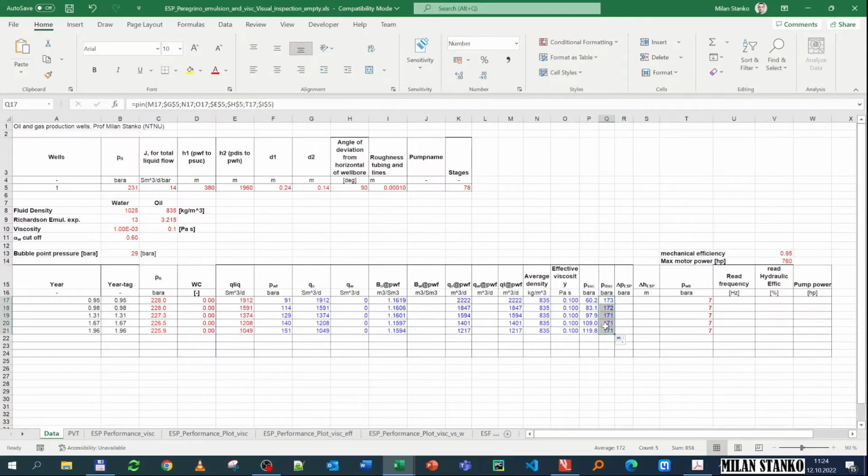And here I require essentially the same for all of them. Okay, 173, 171. So that tells you this is what you required at the exit of the pump, and this is what you have available at the suction of the pump. They are not the same, and this one is less than that one. That tells you that you need to have a pump. So what the pump needs to provide is the discharge minus the suction. Okay, so 113 bar and changing to 89, 73, 62, and 51. So it's reducing a bit with time.